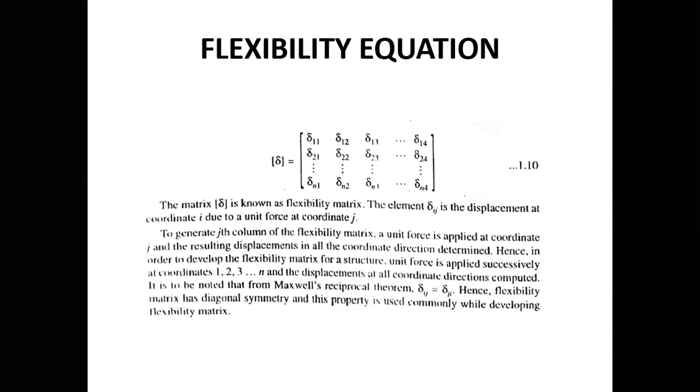Whereas in the case of the stiffness matrix method, we calculate the kinematic indeterminacy and proceed further to calculate the required forces like shear force and bending moment, and do the complete analysis of a structure. So for the flexibility matrix method, we need to calculate static indeterminacy, and for the stiffness matrix method, we need to calculate the kinematic indeterminacy.